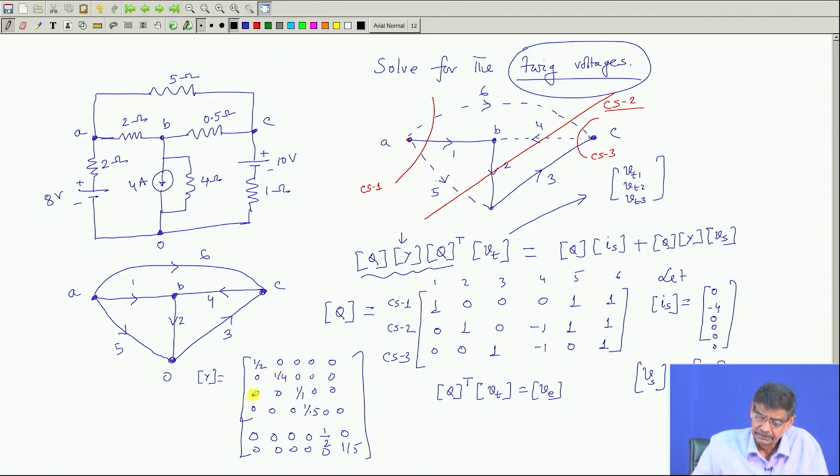In such cases I can avoid the nodal analysis and apply the Z matrix. Z will be finite, Z is equal to 0 if there is an ideal battery across AB. Similarly, there may be a current source only connected between two nodes.